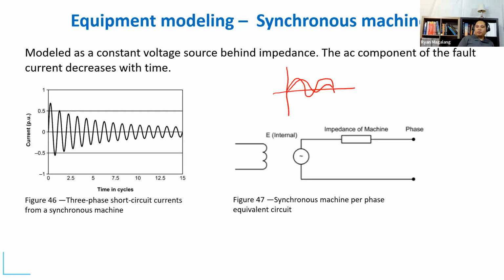So, saying that a synchronous motor's contribution to the fault current would last around 4 cycles, while an induction motor's would last within 2 cycles. And the reason for that is the synchronous motors have their own external excitation, while the induction motors do not have a separate excitation device.